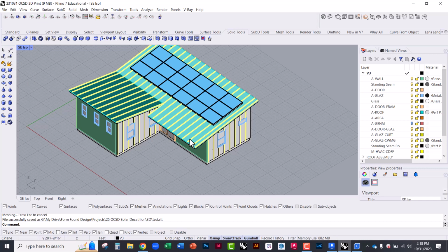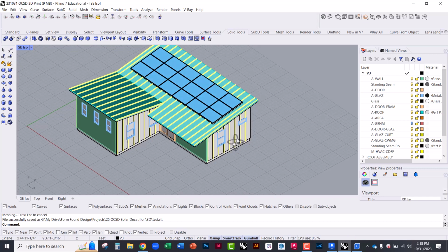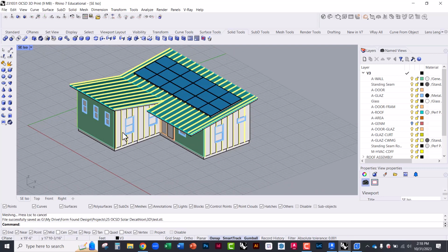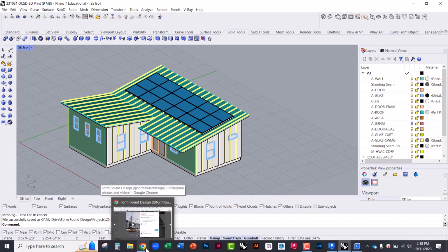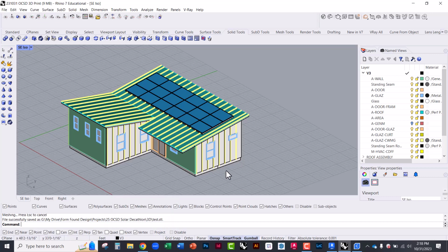The machine is going to take G-code and print the model layer by layer. To understand that, we should understand how the machine is going to read that G-code, what it's doing. It's essentially printing in the X, Y direction, and the 3D print head is moving in the Z direction. So the build plate is going to slowly receive the material, and you're going to build up layer by layer on top of the build plate.